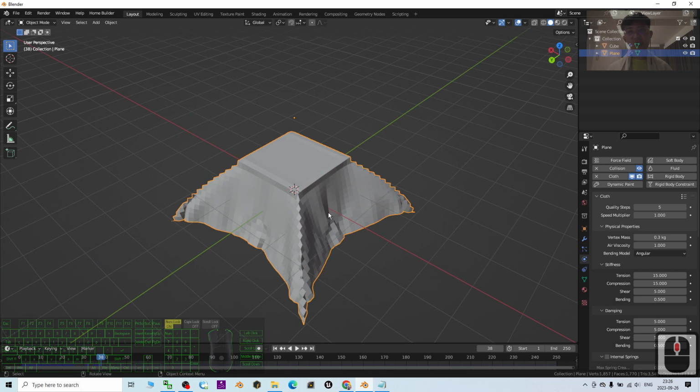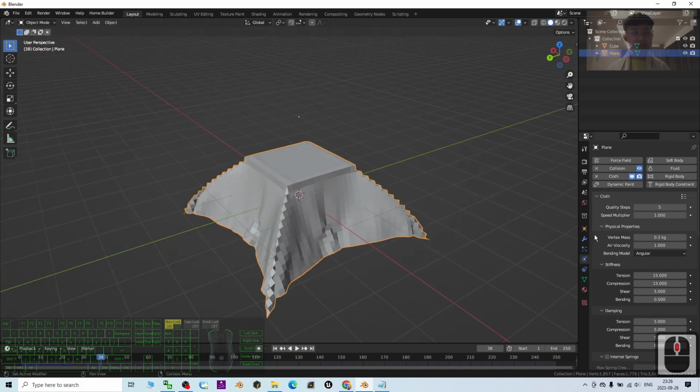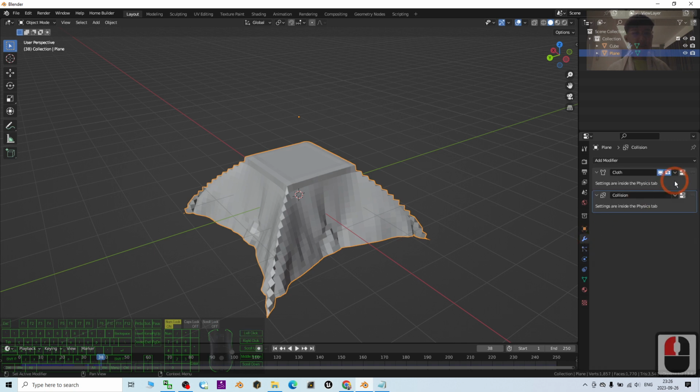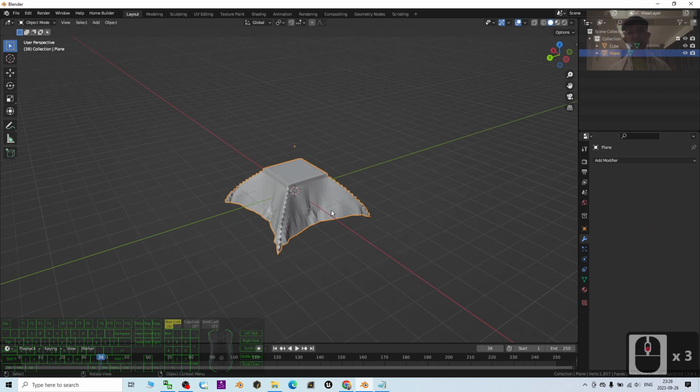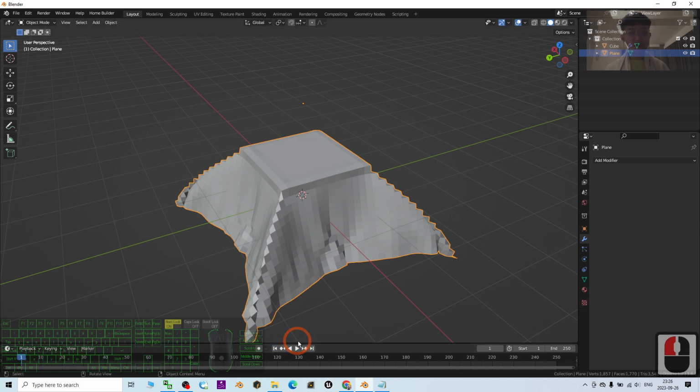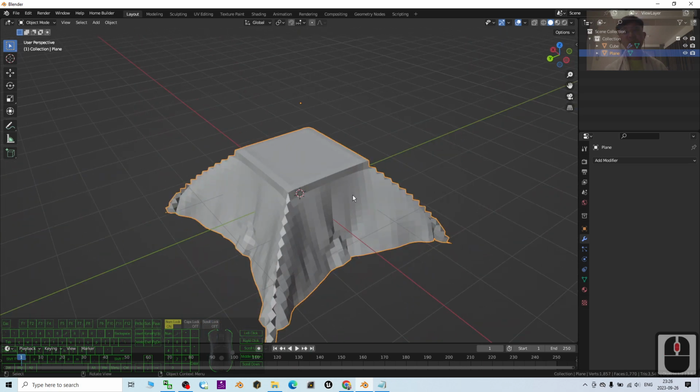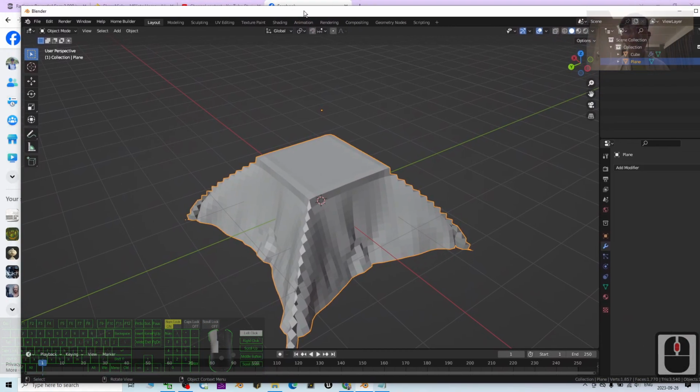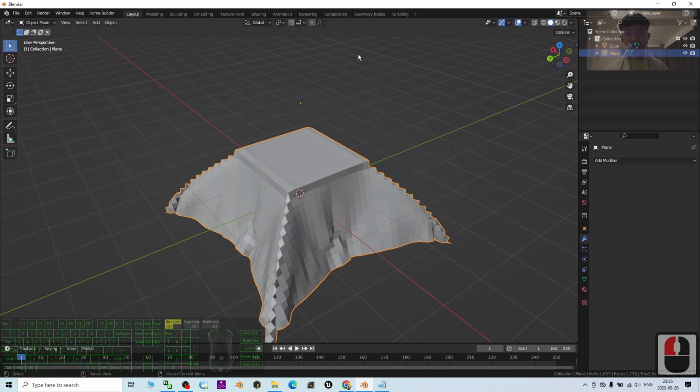So if I want to just make it as a 3D model, then I may just click this soft cloth and just go to the modifier here. I click and apply. Here I click and apply until I clear everything. Then it will become a 3D model. So now even if I go back to the first frame, it is no more simulation, but it already become a 3D model. So if you want to export it as FBX, it is pretty simple.